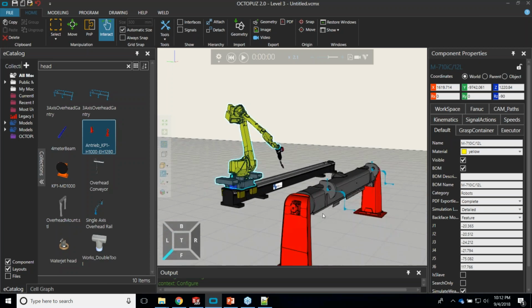Perfect. So a lot of the accuracy issues are something that the more you do this, the more comfortable you are. A lot of our customers are already familiar with offline programming, are already familiar with user frames. They pick that part up a lot faster. The user frame thing can be difficult to wrap your head around if you haven't done them before, but I guarantee you that you are going to get a better result, and you really are going to save time in the end if you spend the time to learn how to do them. And when we're on site, we take the time to show our customers, like I said, best practices.